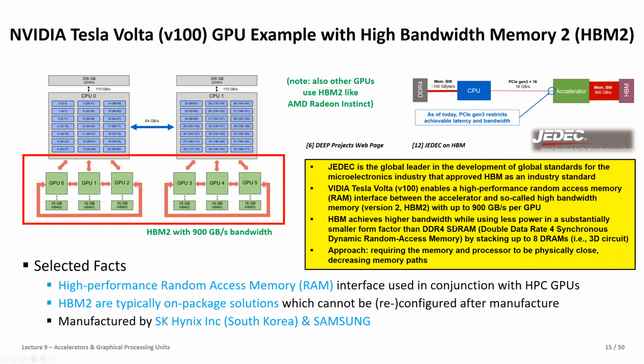However, HBM is there and enables a higher bandwidth than normal, let's say, DDR RAMs that you have there. So that's already helping a lot to make this data throughput that you need for the accelerator really catch up. Still, for fueling, you need a really good strategy to always bring into the device memory the data that you want to compute.